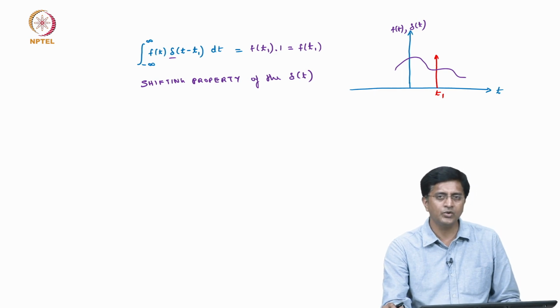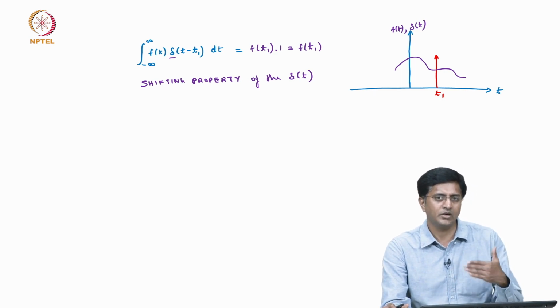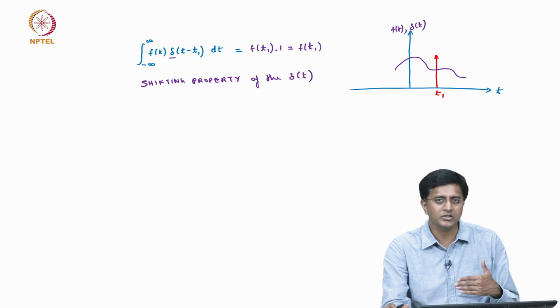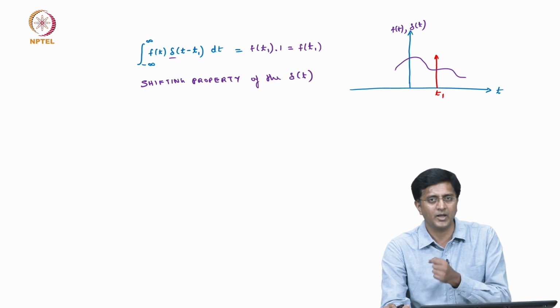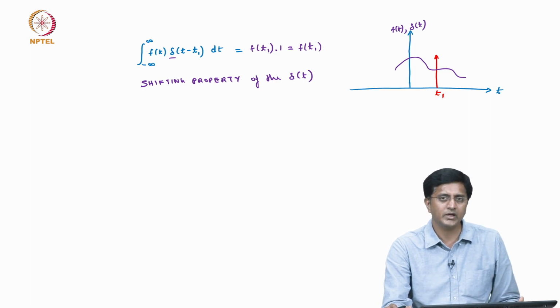Now, we said when we talk about viscoelastic models, either they can be represented as a differential equation or as an integral equation. But when we have these differential equations, it becomes easier if we solve them in the Laplace domain. So, let us quickly look at what Laplace transforms are and how we solve them.